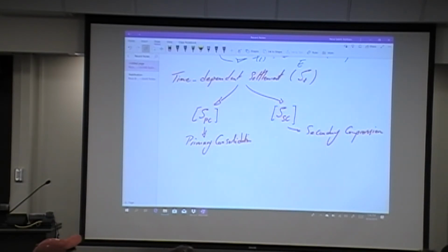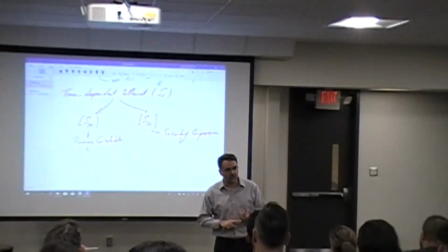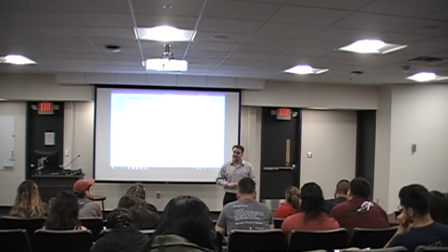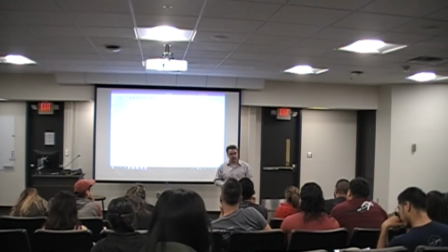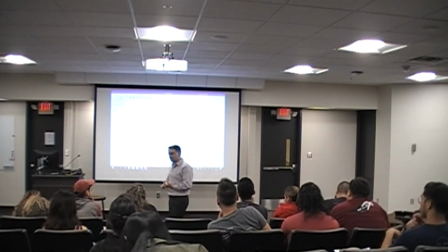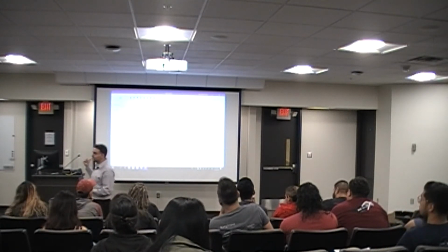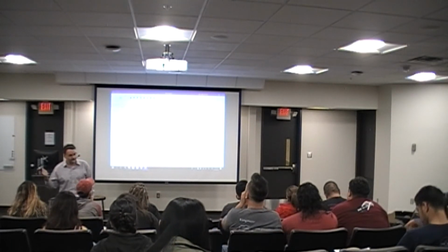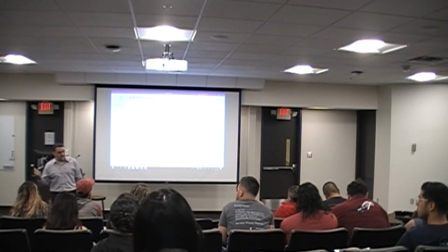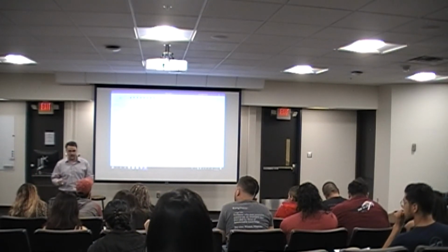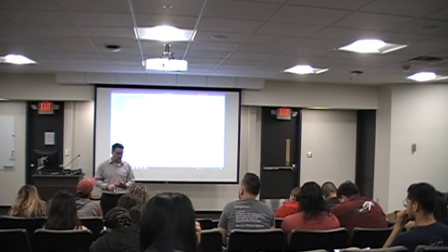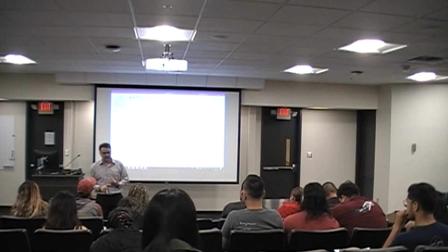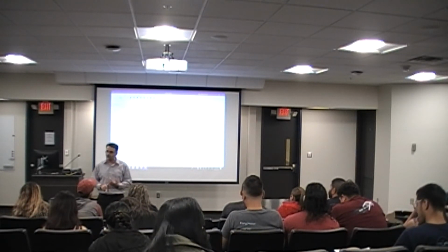Let's go back and take a look at what we talked about so far. Remember we talked about the immediate settlement. Immediate settlement happens at constant water content, right? And that's the predominant mode of deformation in unsaturated soils. That's also something to note. The second one, or the second category, has to do with the time-dependent component of settlement. So you have the time dependency. You can just basically subcategorize it into two main categories. Category one would be primary consolidation, and the second one would be secondary compression. Now tell me, primary consolidation, does it happen at constant water content or variable water content?